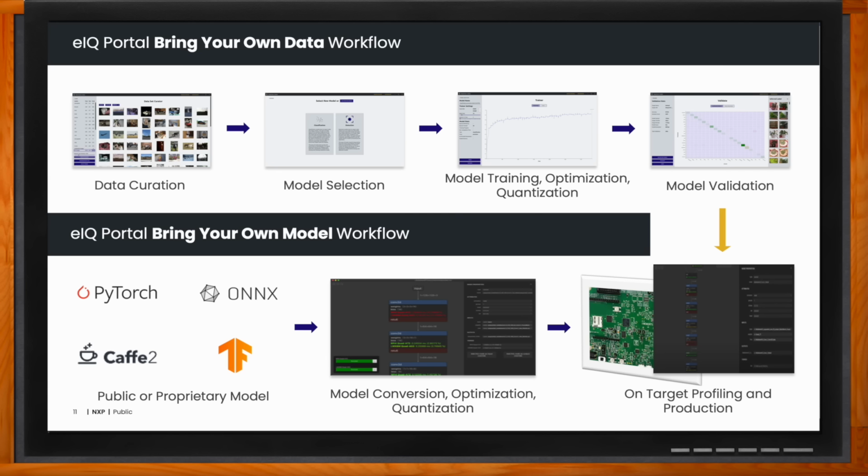So I won't go too much into technical details, but essentially if you said something like PyTorch, you can convert it from PyTorch to ONNX to TF Lite, and that can go on the i.MX 93. It also has a great visualizer, so you're able to see, hey, what's in this model, what's the input size, what's the output size. Personally, it's a really great tool to just look at a model and see, oh, something's gone wrong, and half the time it's the wrong input size or something. So it's a great little tool to visualize a model, but also to convert the model from wherever you're taking it and port it onto the i.MX 93.